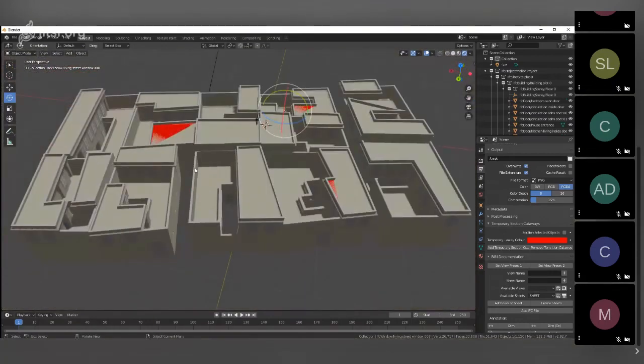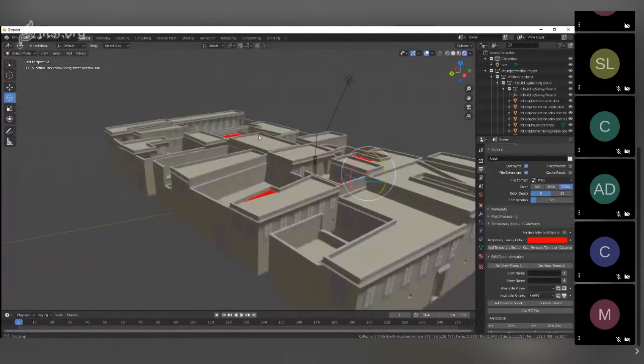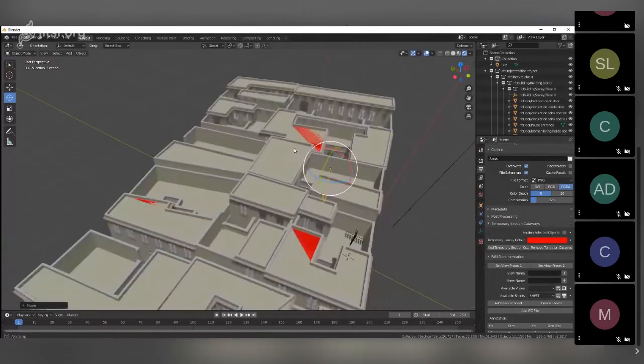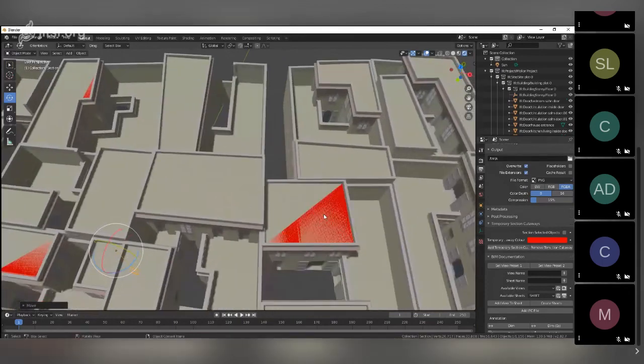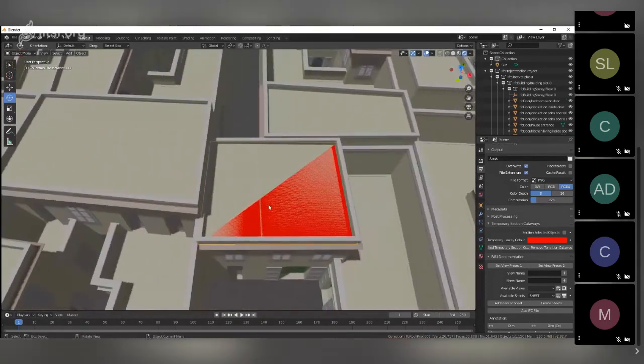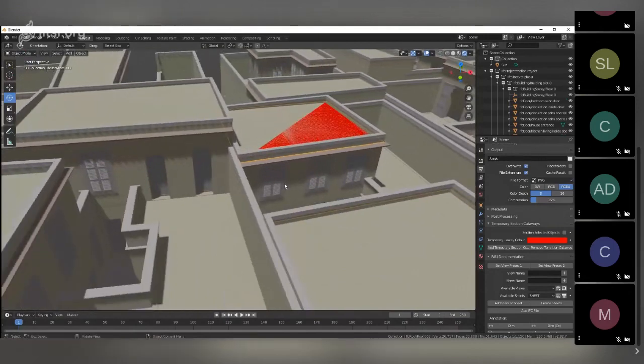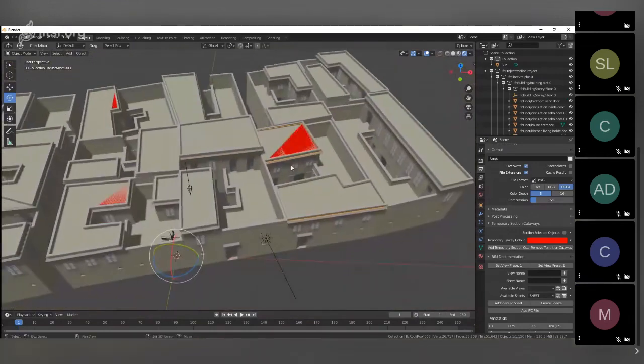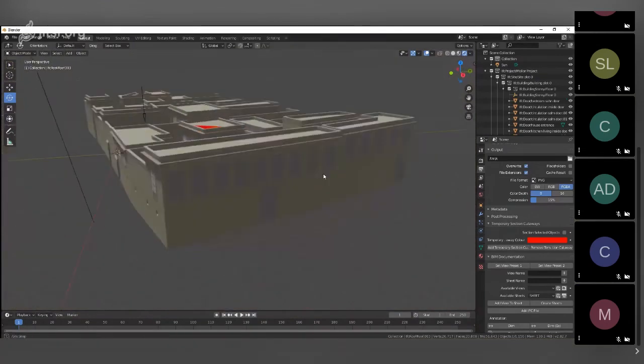Anyway, this is a model. I've explored it. I got it working, and then I kind of abandoned this one. Haven't done much more on it since. These red marks are glitches because the flat roof is a very thin wedge, and the import from IfcOpenShell comes in triangulated, and Blender BIM is merging triangles into quads, and it's got that one slightly wrong. But it's not a big deal, obviously.